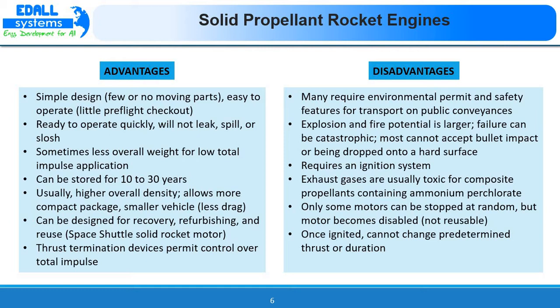Then it requires a different ignition system. Exhaust gases are usually toxic for composite propellants containing ammonium perchlorate. So for the propellants which include ammonium perchlorate as their fuel or oxidizer, the exhaust gases are very toxic. Then only some motors can be stopped at random, but the motor becomes disabled, that is, not reusable.